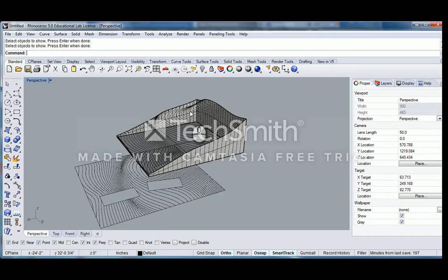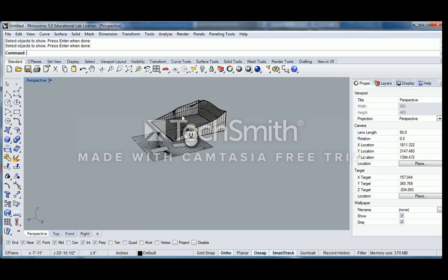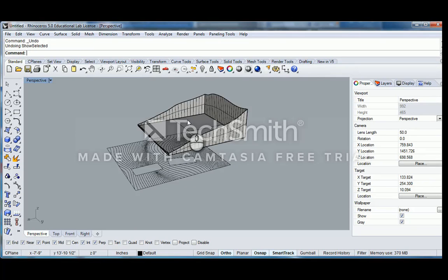Do you always have to use this oriented C-plane to go through vertically? You don't have to do that. We could cut the contours the other way if you wanted to. You wouldn't have to change the C-plane. It was just a quick, easy way to make sure that we were pointing vertically. It will cut it based on that C-plane orientation, if you don't give it an override.